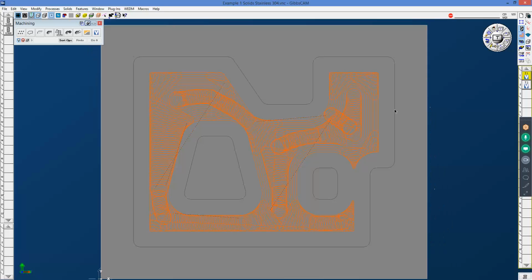But now they've added a new functionality whereby they say, if I'm going in a pretty large area, I'm going to do a spiral, like a 2D helix, out from that as far as I can, and then I'll switch to the slotting algorithm because that's much more efficient.